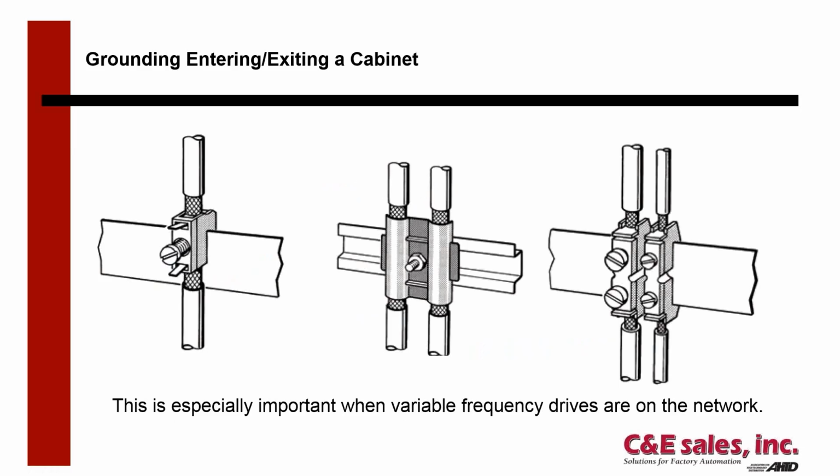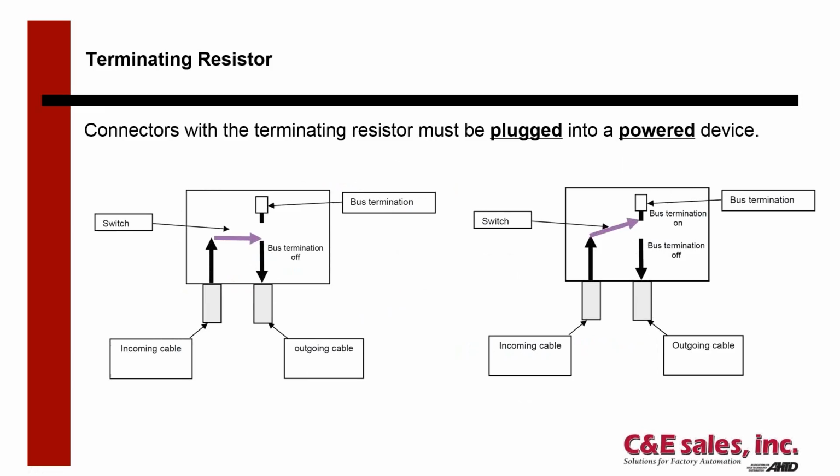I've actually had a number of customers over the years who say, hey, I've got a Profibus network and it's pretty good, but every time we start this drive, we start losing communications, and it is typically the shield problem here, okay?